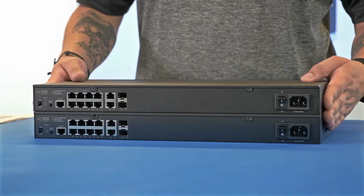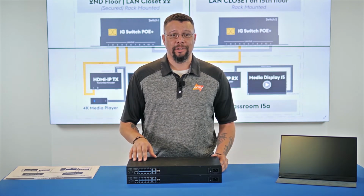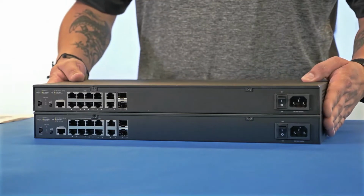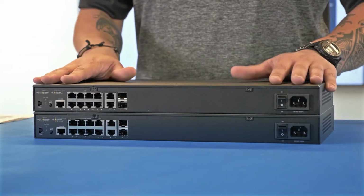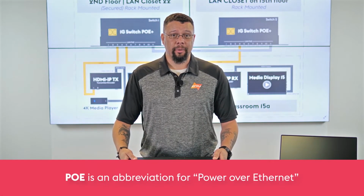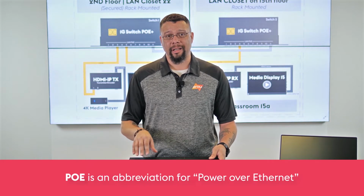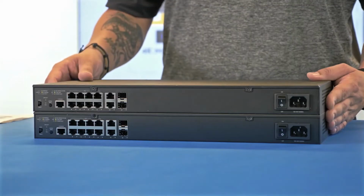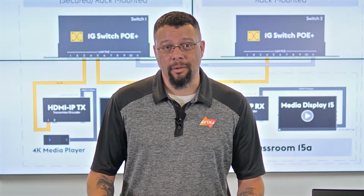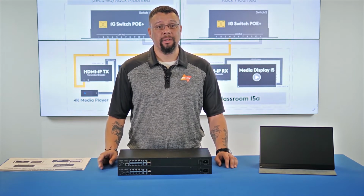Here we have two 12-port multi-layer AV switches. Sometimes multi-layer switches, like these, are also called layer 3 switches. These are fanless, which is a valuable component in an AV installation where we want silent operation. Now this switch also supports PoE. I verified that the switch supports the power requirements of both the encoder and decoder we will be using. For production, you will need to conduct PoE power budgeting. We sent this model to the IT department weeks ago, and it was certified by their IT security personnel to be within their parameters.